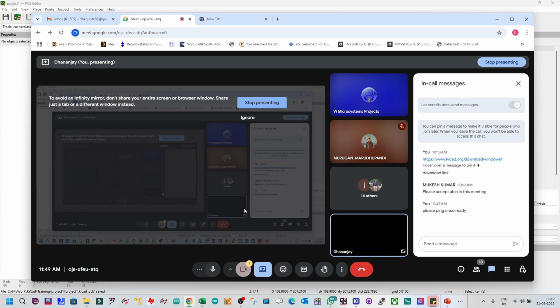I mean, for placing components during production, to read the ref des, like D1, D2, D3, where those are, their outline, their symbol will be there, so that you can place all those. There will be one alphanumerical layer, and one logical, symbolic drawing for all the components.